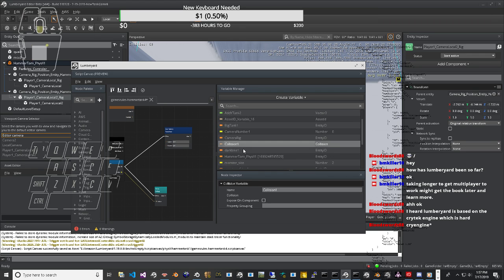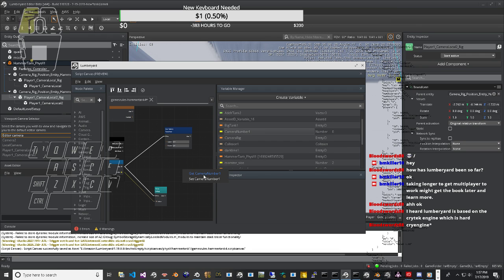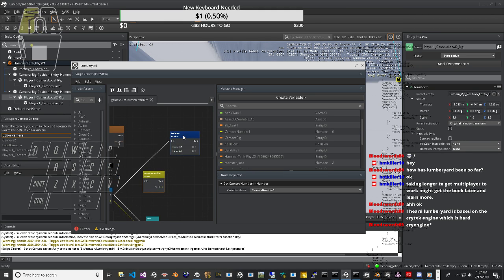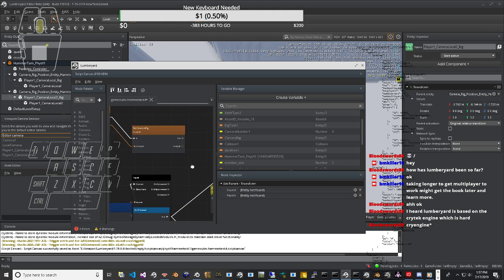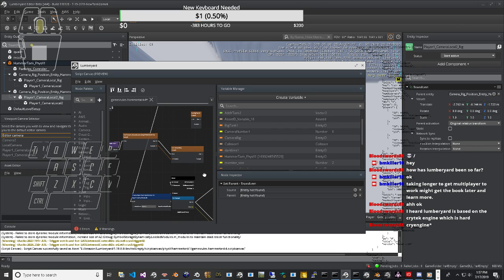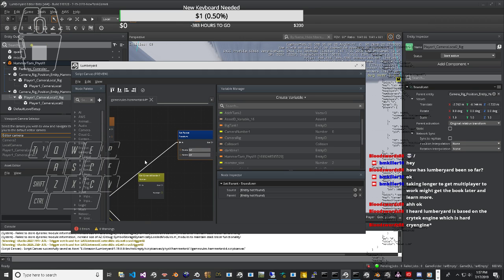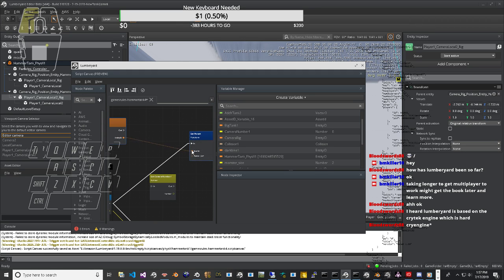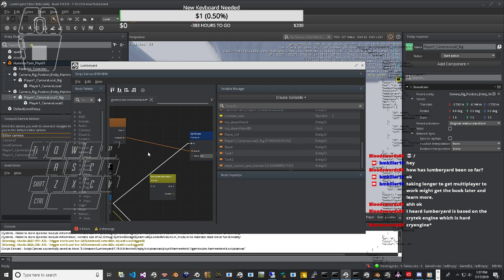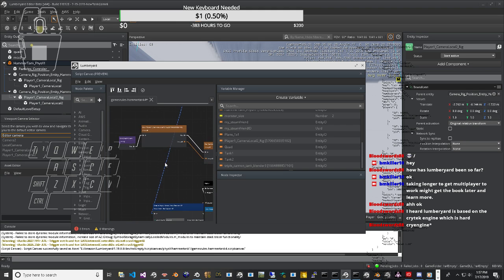More important is the orientation of WHE. Consider the plane occupied by the wheel itself. This plane intersects ROAD in a line that defines the x direction of WHE, with the positive direction being as close to that of travel as possible. The y direction points to driver's right. The wheel plane is tilted by a camber angle about the x-axis of the wheel coordinate system. To emphasize, WHE does not include wheel camber, and it differs from ROAD only by a rotation about ROAD's z-axis that accounts for the pointing direction of the wheel.